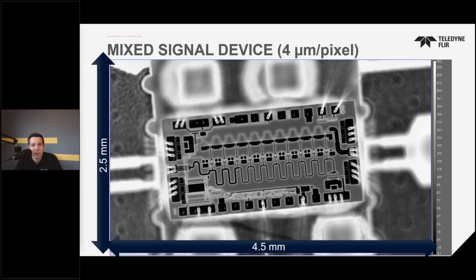But this device was experiencing a problem, and unfortunately, even with this level of magnification, we really couldn't identify where it was happening. This is where extreme sensitivity even needs a little help. So we recorded power being applied to the device, and then performed an operation called image subtraction, wherein you subtract the pre-powered image from the powered frames, and now you only see the delta. So you can see how having a very sensitive camera will provide smaller deltas to be measured. So that sensitivity definitely helps for identifying these very subtle changes.